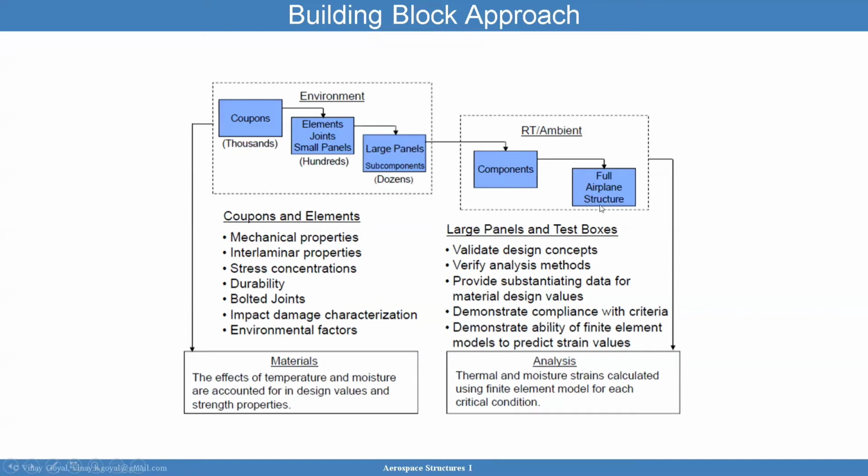And again, why I need the analysis to match the test. We need to understand that because you may say, well, the test is just enough. But the reason you want to make sure that the analysis is doing a good job is because the analysis is your transfer function between the testing on the ground versus the flight condition. Remember, the boundary conditions are different.